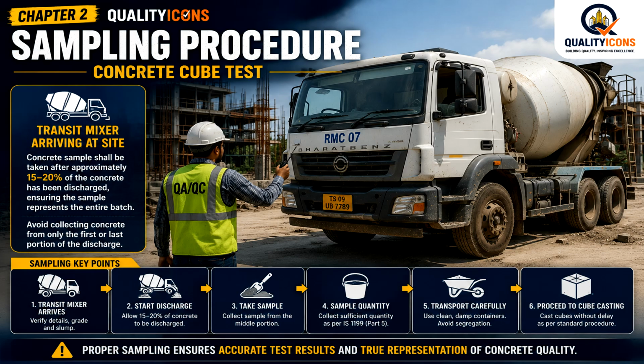So coming to the next step, what is the sampling procedure? What are the methods and requirements? Concrete sampling begins when the transit mixer arrives at the site. Never collect concrete from the first or last discharge. As per Indian standard practice, collect the sample after approximately 15 to 20% of the concrete has been discharged. This ensures that the sample truly represents the entire batch. Proper sampling is the first step toward obtaining accurate strength results. Please remember it.